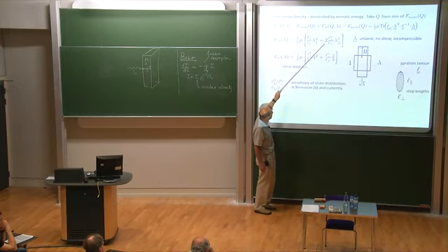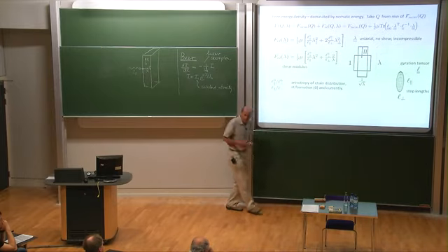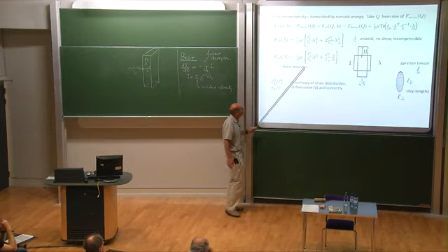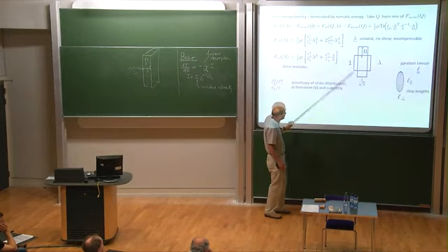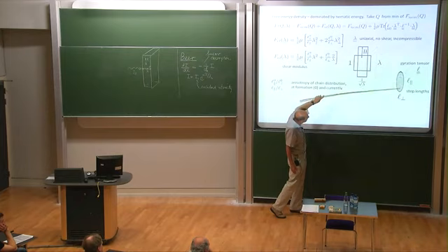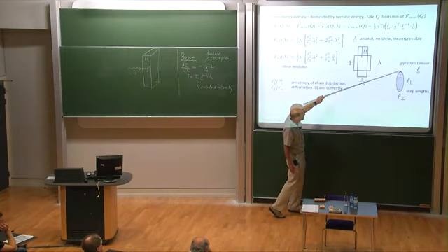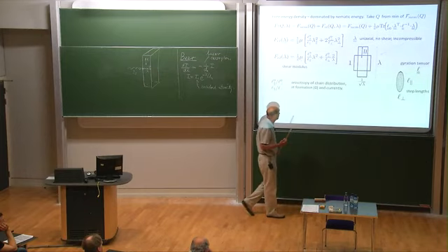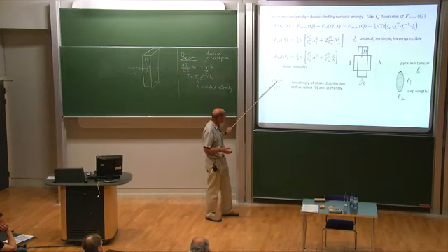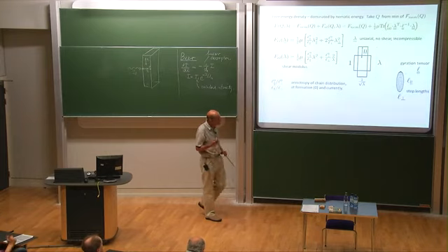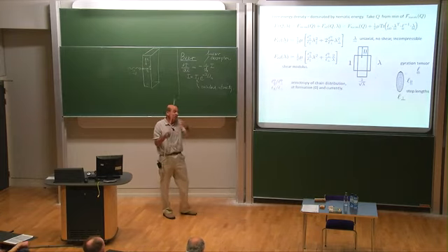And there are two perpendicular directions, which is that 2 there. And I have the ratio of the parallel length of the distribution initially divided by the parallel length of this distribution currently. So these are the anisotropies of the polymer distribution that makes up the rubber.